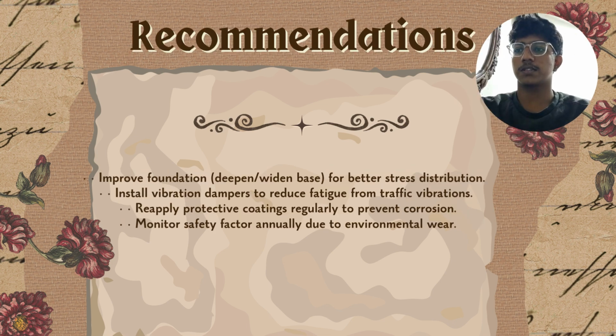Next, to improve the structure further, we recommend upgrading the foundation by either deepening or widening the base. This will help with better stress distribution. Adding vibration dampers is also advised to reduce the fatigue caused by constant traffic vibration. Protective coating should be reapplied regularly to avoid corrosion and extend the pole lifespan. Lastly, the safety factors should be monitored yearly because long-term environmental exposure can slowly weaken the materials.